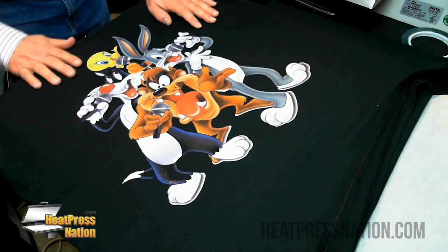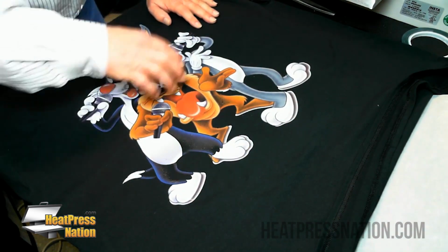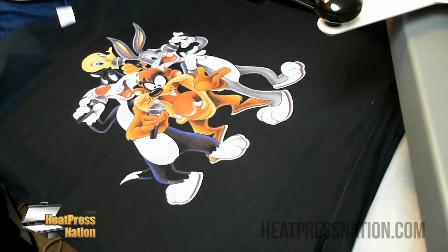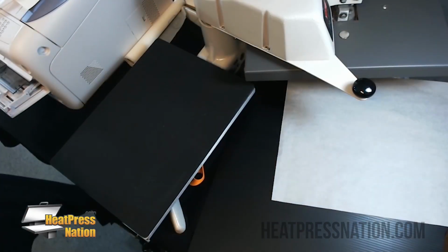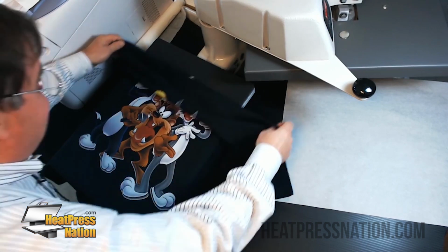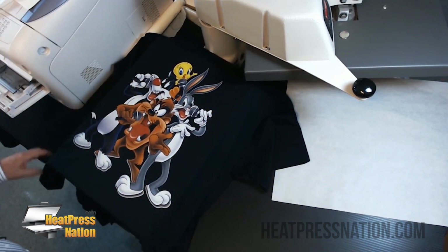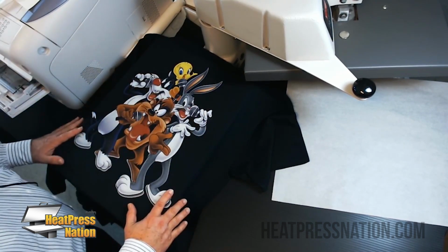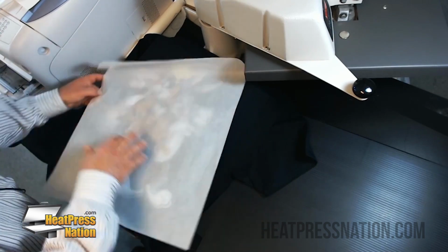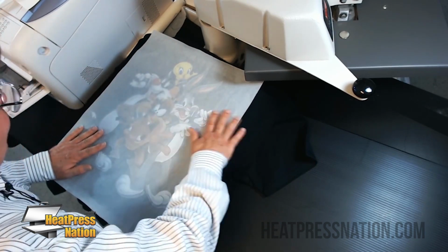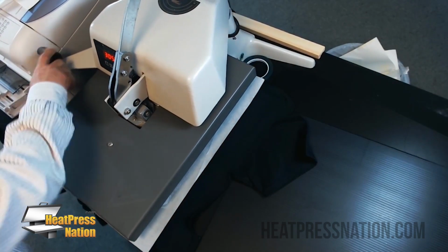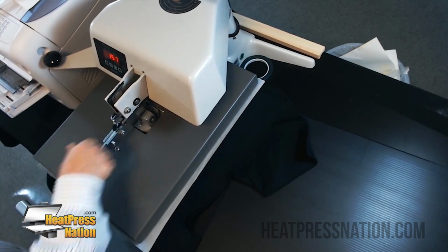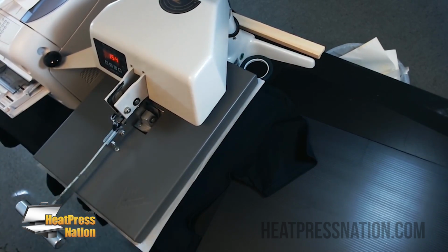So now here's our design, middle piece, top, bottom. So we want to press this one more time. Actually, we may have to press this 2 more times because it doesn't all fit on the heat press. We want to get as much of it on as we can so that we get the main part of the design pressed in, and then we will come back and get the edges. So we know now we go to high pressure, and we're pressing this high pressure for about 30 seconds.